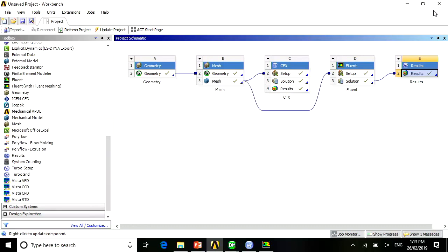You can change your language, but it's based on physics again. It's what velocity you put in. 1 meter per second is more than 2,000 Reynolds number. Yes, I know it's turbulent. That's why I put 1. I can put 10, and I know it.